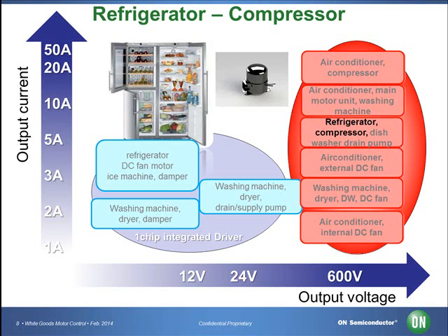ON Semiconductor offers Intelligent Power Modules, or IPMs, for three-phase motor control. These IPMs use the ON Semiconductor unique insulated metal substrate technology, IMST, which offers high efficiency, high reliability and safety, often with an overall BOM cost savings. These motor drivers utilize hybrid IC technology, which provides the highest current output solutions on the market today. Compared to traditional discrete solutions, ON Semiconductor's IPMs provide a smaller component count, reduced board space, increased reliability, and lower heat dissipation.